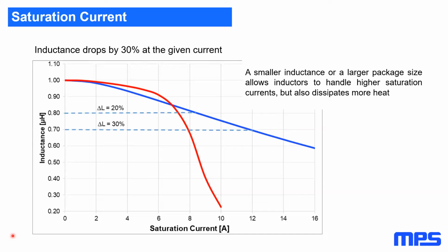There are other manufacturers not controlling the start of the winding position and just indicating such a dot or a bar for absolutely no value. As a high quality supplier, MPS takes care that all products show the start of the winding in the correct way. Please always take care to place the start of the winding close to the converter switch nodes.